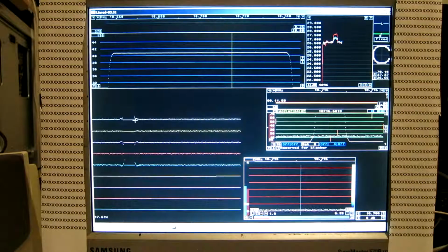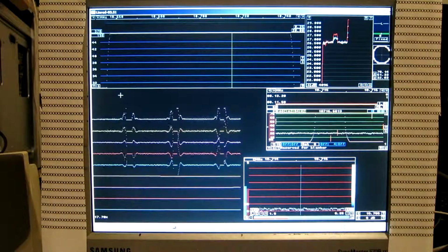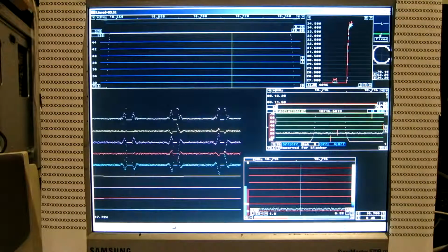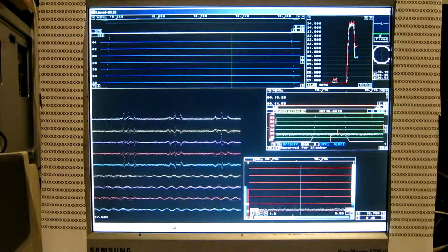But now we are cutting a big hole here. That is 4% of all the data. With a higher pulse repetition frequency, like this, now it is the dumb blanker. It removes 9%. We have quite a bit more interference. Add the smart blanker. You can see it makes a difference. You can bring down the threshold for the dumb blanker a little bit.